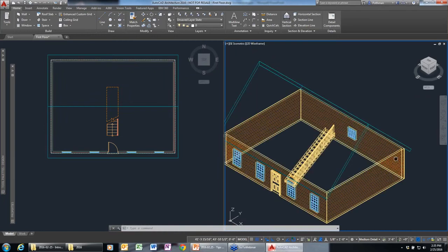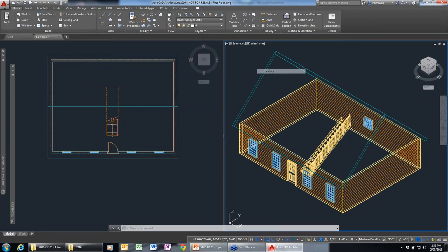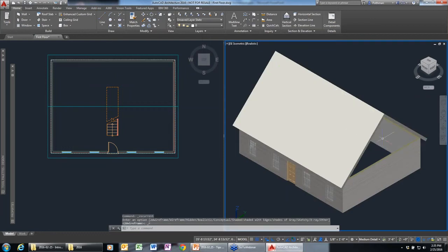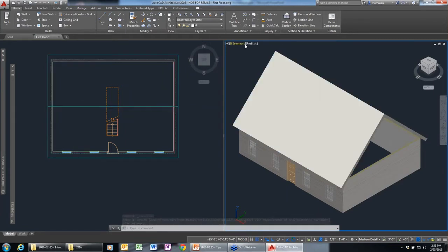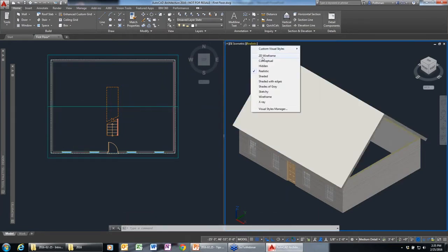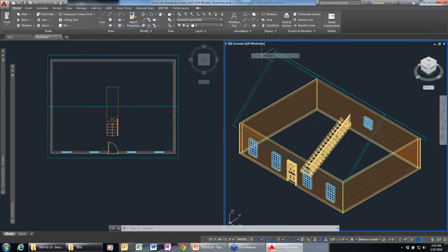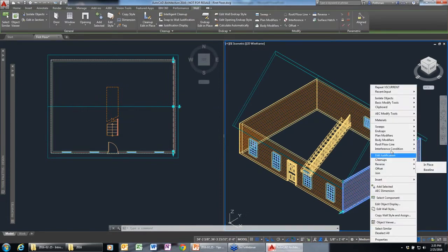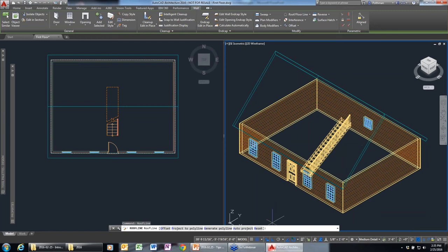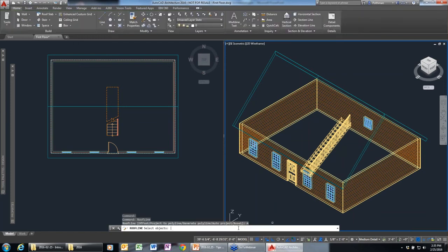Of course, I'm still going to get wet if it rains because I have this big hole here between the roof and my wall. So I'm going to go back into my wireframe, and I'm just going to pick on the wall. Again, remember the contextual tabs and such? There's also, by the way, the same kind of commands in the right-click menu. And I'm going to go to this roof floor line pull down here, and I'm going to say I want to modify the roof line. And what I want to do is auto project it to my roof, right?